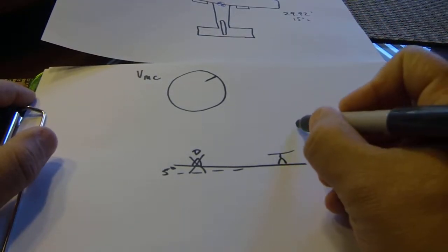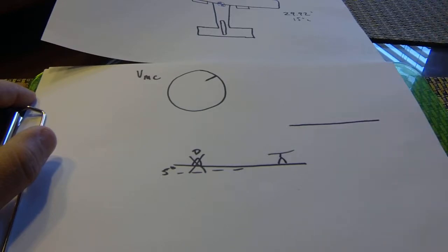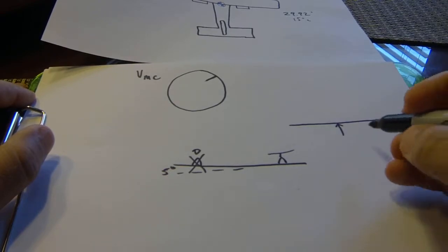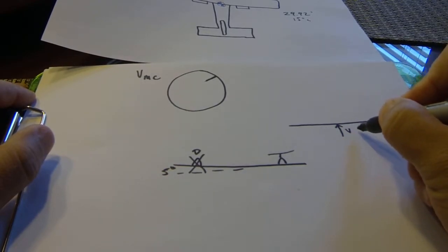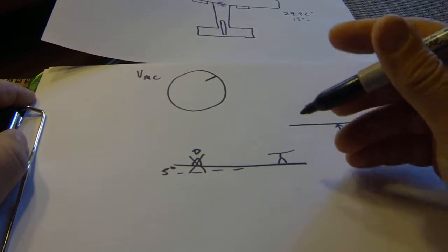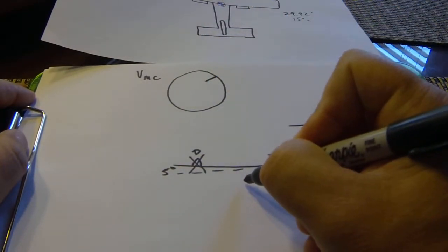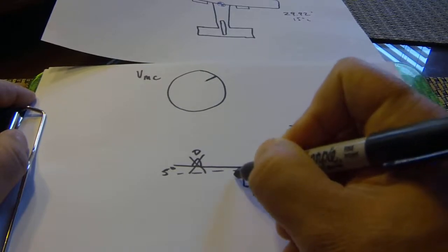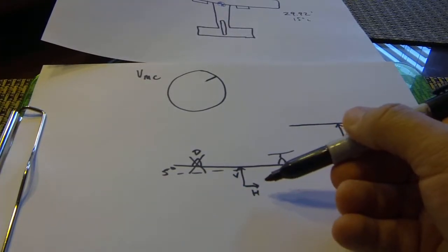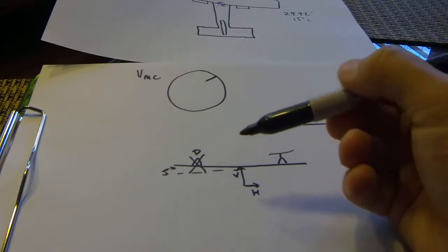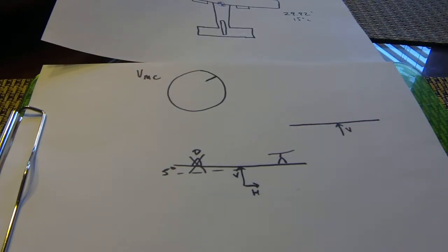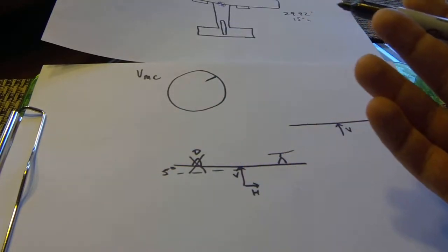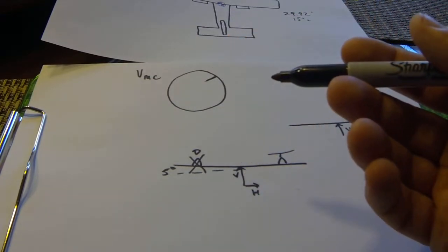Remember, lift in perfectly straight and level flight acts perpendicular. We have a 100% vertical component of lift. As we bank the aircraft, we now have not only a vertical component of lift, but also a horizontal component of lift. And this horizontal component of lift gives us a slight advantage. Well, it's more than slight. It provides a distinct advantage to rudder control and authority.